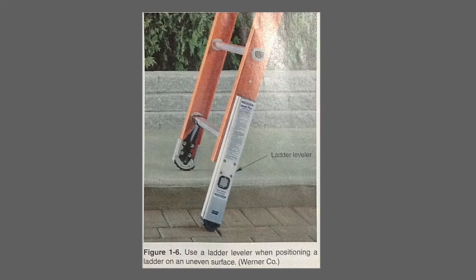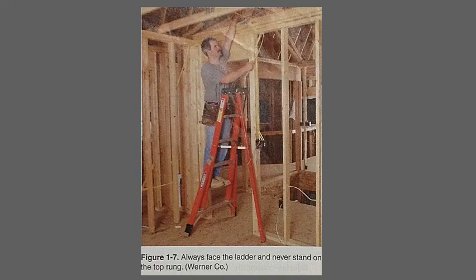Step ladders should be set level. They must be fully opened so the hinges will lock. Never use a step ladder while it is leaning against a structure. Always open the ladder. Keep the joints tight so the ladder does not wobble or lean. When working on the ladder, always face it, such as in figure 1-7. Never use the top rung or step of any ladder for support. Check ladders often for step rot or other structural damage, and make sure to discard ladders that are in poor condition.